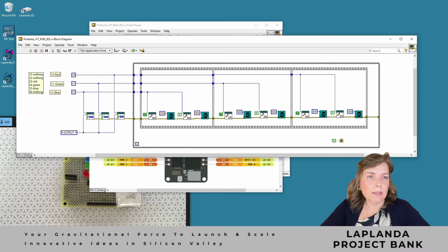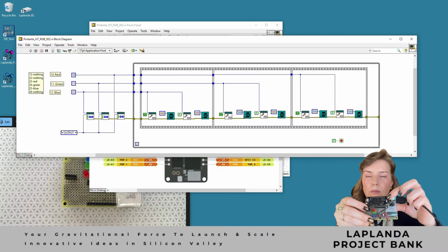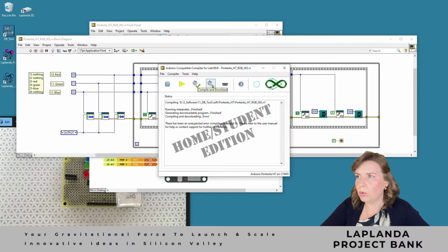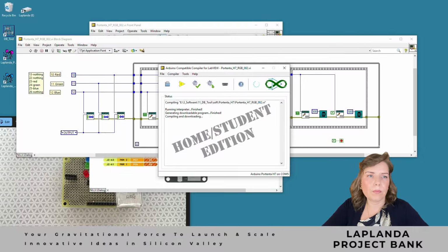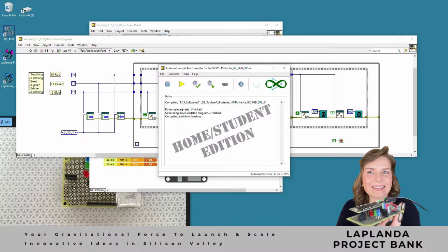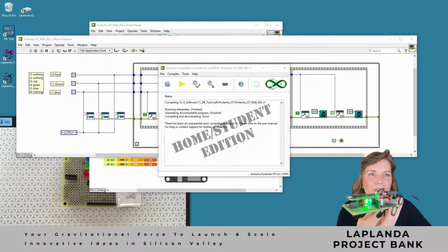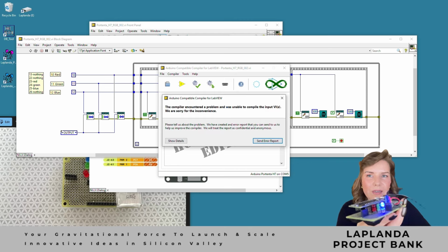Don't forget to press the reset button to activate bootable mode. Yes, now we can clearly hear that boot mode is enabled. And I launch my compiler. As you can see, the 3 LEDs on the evaluation board have started blinking. This means, as real engineers would say, we have successfully flashed the board.